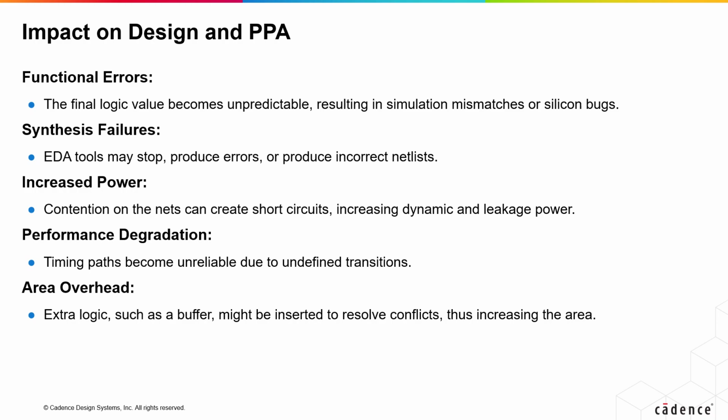The creation or presence of multi-driven nets in the design impacts power, performance, and area. Multi-driven nets can make the final logic value unpredictable, leading to bugs in silicon. During synthesis, multi-driven nets may be generated, which can stop the process, cause errors, and produce an incorrect netlist.